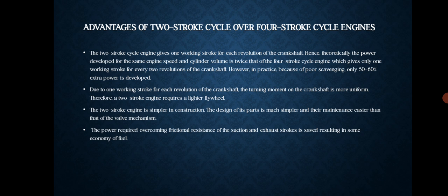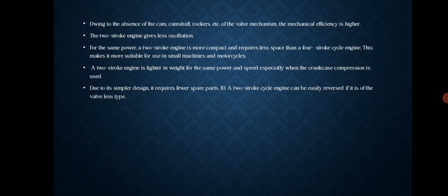The power required to overcome frictional resistance of the suction and exhaust stroke is saved, resulting in some economy of fuel. Owing to the absence of camshaft, rocker, etc. of the valve mechanism, the mechanical efficiency is higher. The two-stroke engine gives less oscillation.